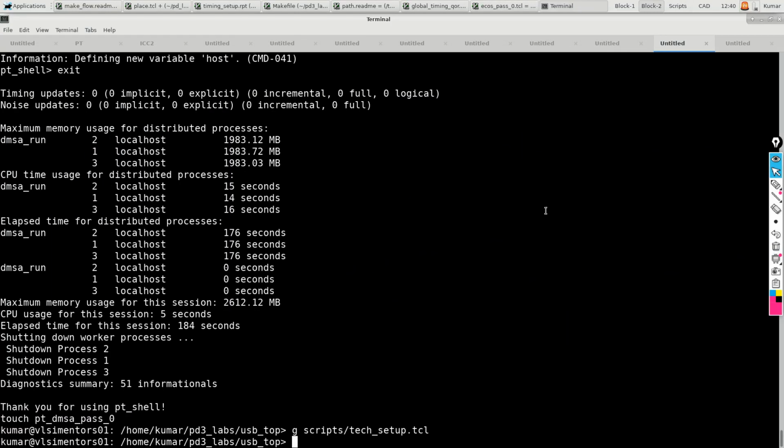Okay, I wanted to spend some time on the questions that are in the chat box. I'm just coming from the top. Macro placement guidelines: each macro comes with certain guidelines. There are poly requirements, OD requirements. You have to honor that. That is the main thing.